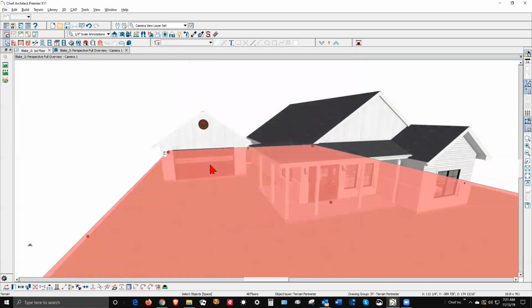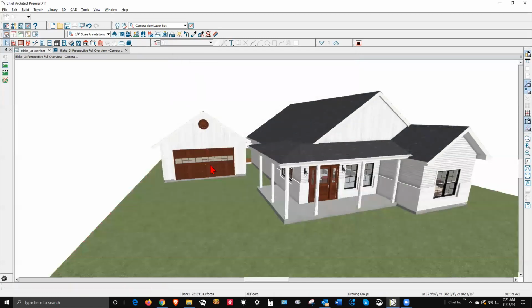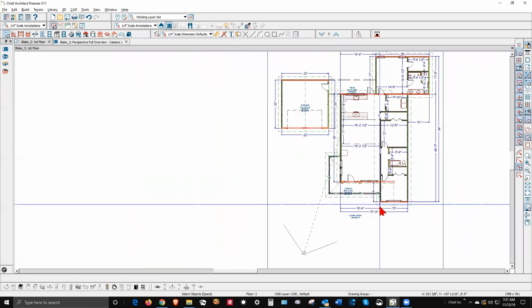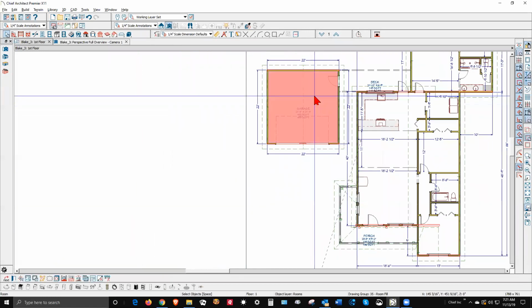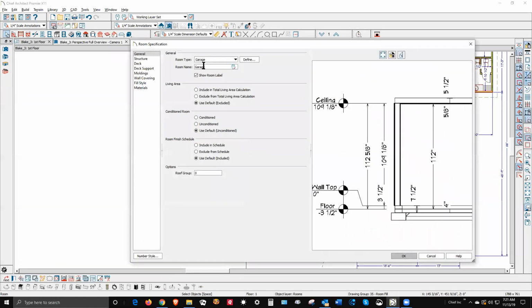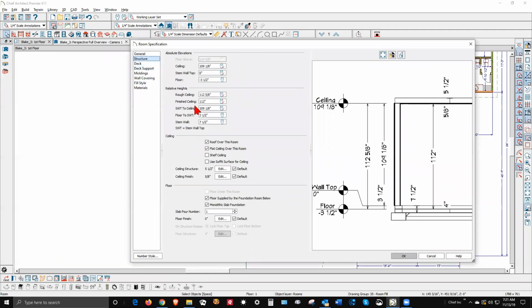And usually the garage is lower because the garage is at ground level, so you can just drive into it. So I usually set the garage a little bit lower. Let's open that garage dialog box. And you can see it's at 0 inches. Oh, I'm sorry. Okay, it's at -3.5. I usually set -6 because the floors of garages are slanted.